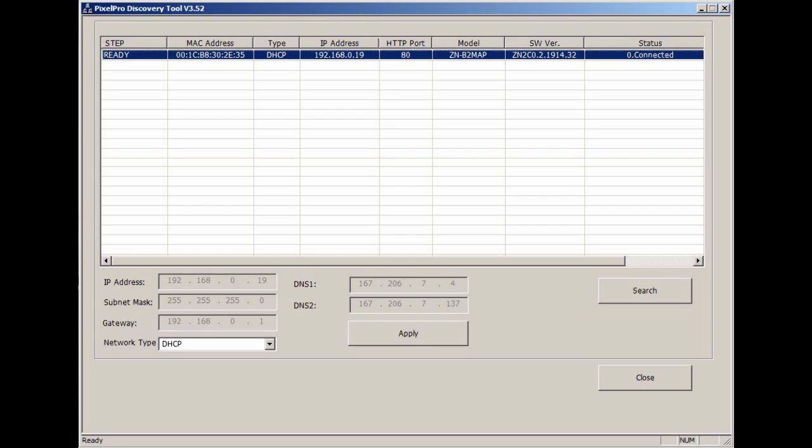First, check and confirm the camera is getting power. This can be confirmed by way of a solid green LED on the camera. If the camera is confirmed as getting power, then the next thing to check is any running firewall program on the PC. Be sure to turn off any and all running firewalls on the PC in question. Third, check the Cat5 cable for any damage. If a switch or hub is used, check for a possible bad port by moving the camera and or PC over to another port.